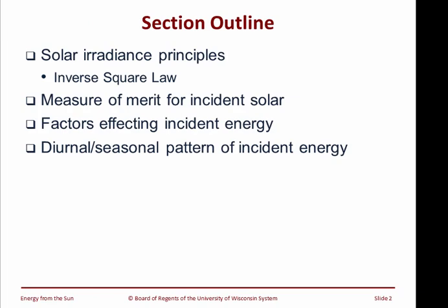First, I will be discussing the solar irradiance principles, including the inverse square law. Then I'll discuss very briefly the figures of merit for incident solar energy. In addition, I'll be talking about factors affecting the incident energy. I'll also touch on the diurnal or the seasonal pattern of the incident energy.